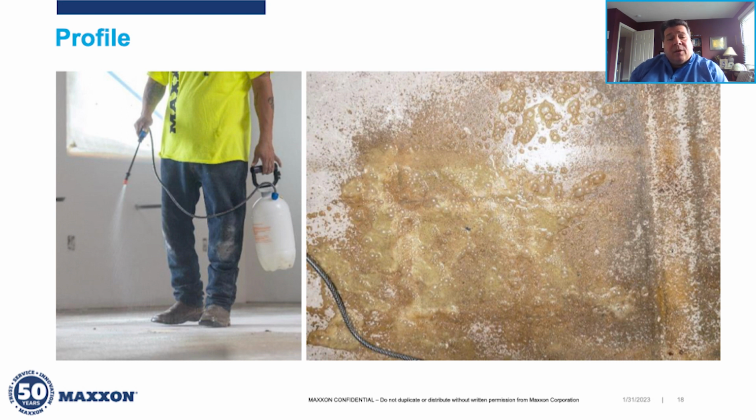And then the method of removal could be one of three things. If you are fortunate enough to be working in a space where there is a floor drain, you can basically flood the water to the drain with a hose or a power washer. If you're working in a smaller space, then you could flood the space with water. Use a squeegee along with a good shop vac, a wet dry shop vac to remove the solution. Or if it's a larger space and you have access to an auto scrubber, that would be the ideal method of removal there.